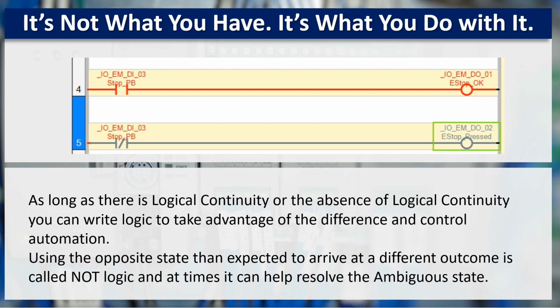If you don't have it, don't energize the rung. But if we change the state of the stop, now we know that the stop has been depressed. So we can use both sides of any contact. We can use a 0 or a 1 anywhere in our program, depending on how it's to resolve our logic.